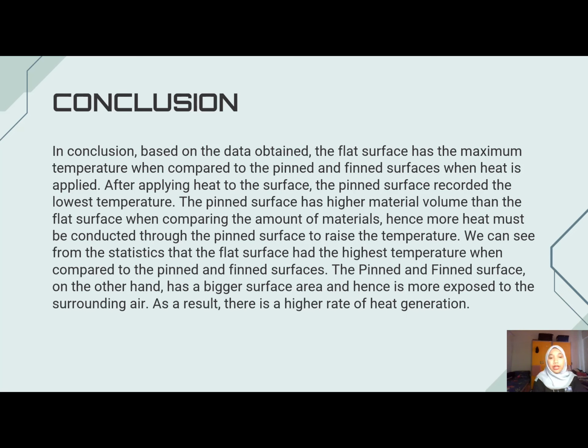Hence, more heat must be conducted through the pin surface to raise the temperature. We can see from the statistics that the flat surface had the highest temperature when compared to the pin and fin surface. The pin and fin surface, on the other hand, have a bigger surface area and hence are more exposed to the surrounding air. As a result, there is a higher rate of heat dissipation.